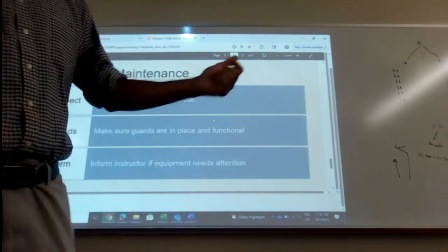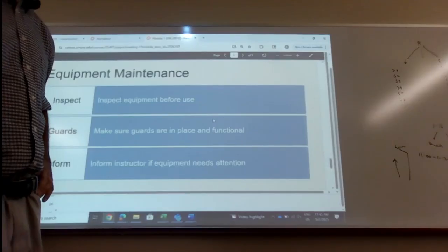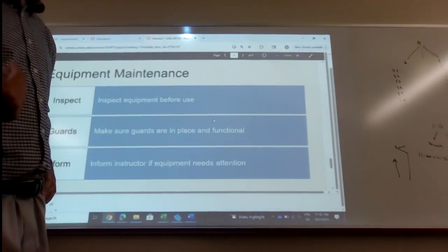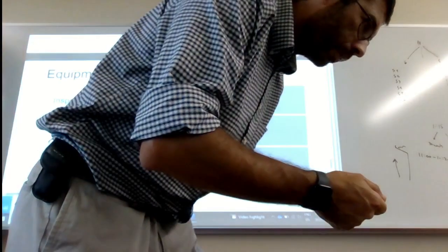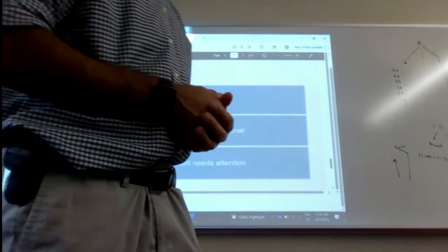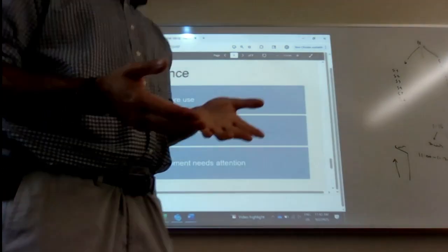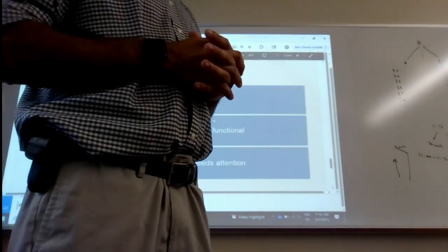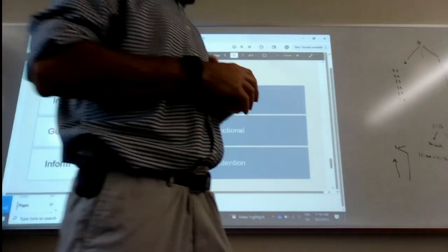Oh, I turn on this equipment, oh, it dies, I turn it off. It didn't kill anybody. But for example, the grinding wheel, if I turn it on and go to grind right away, then if it pops, your face is right in there. So you turn it on and wait for it to reach max speed, and now it can work. That means it's safe. If it's going to pop, it's going to pop right away, before I reach max speed.